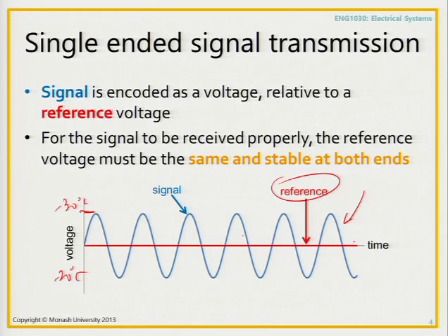Usually, we'll connect our reference point to an earth or ground circuit, so that might correspond to physically a wire connected to an earth stake, for instance, which is a copper rod that you chuck into the ground, and you might, for your mains power at home, have a copper rod outside somewhere, and you would connect a wire to that, and that would be the ground of all the electrical hardware in your house. So that's good because you would have a reference.